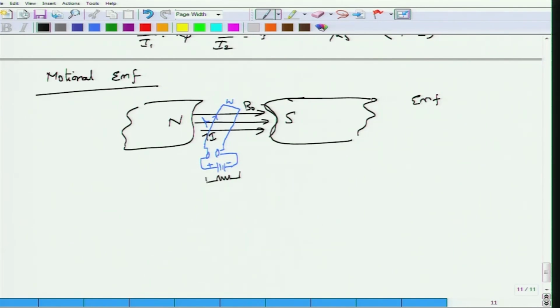or you can remove the battery and put a load resistor. In one case you are actually generating DC. When you put a load resistor, you are generating a DC voltage. The commutators are chosen in such a way that when there is a half rotation of the coil, the commutators switch places so that the overall direction of the voltage stays the same. Otherwise the voltage would be 180 degrees opposite to the original voltage. You would get an AC voltage, but if you want a DC voltage, you flip the commutators at the right time such that the voltage polarity is always unidirectional.